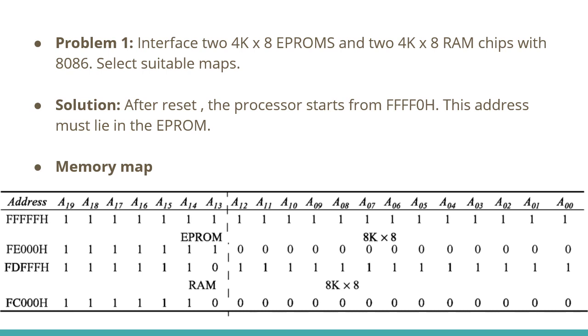The remaining higher order address lines, that is, from A13 to A19, are used for decoding to generate the chip select. The BHE bar signal goes low when a transfer is at an odd address or the higher byte of data is to be accessed. Let us assume that the latched address, BHE bar and demultiplexed data lines are readily available for interfacing.